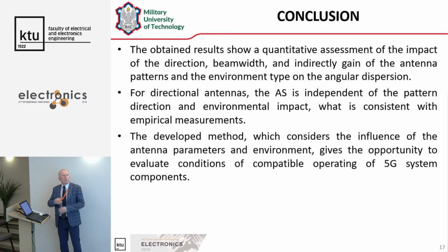Conclusions. The obtained results show a quantitative assessment of the impact of direction, bandwidth, and indirectly gain of antenna patterns, and of the environment type, on the angular dispersion. For a directional antenna, the angular spread is independent of the pattern, direction, and environment impact, which is consistent with empirical measurement. The developed method, which considers the influence of the antenna parameters and environment, gives the opportunity to evaluate conditions of compatible operation of 5G system components.